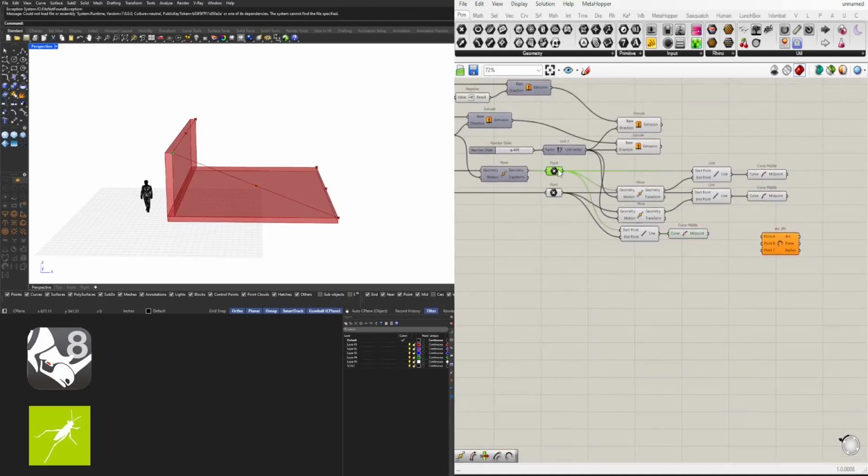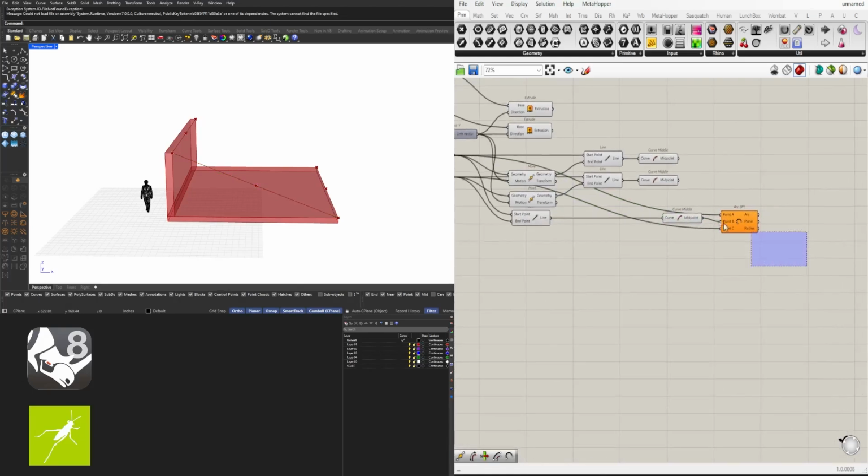But if we were to use these as the arc 3 point, notice that the midpoint is going to be point B. The first one is going to be either one of these points, and this is going to be the last one. It just creates a line segment because there's no variation in the point here. So what we need to do is scoot this over where the midpoint is for the center, and I'm going to offset this line segment.